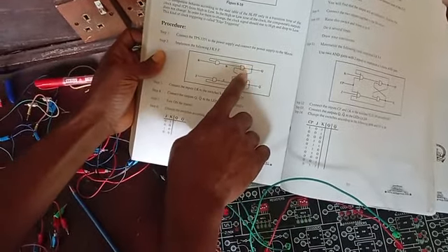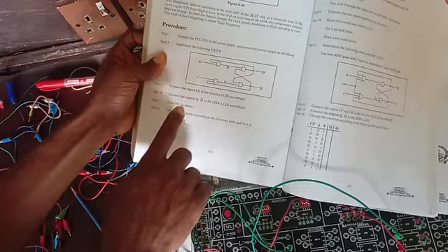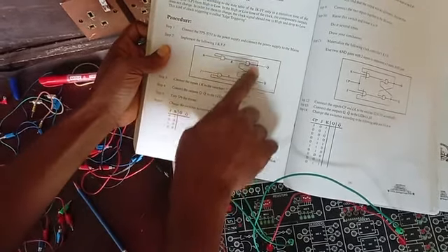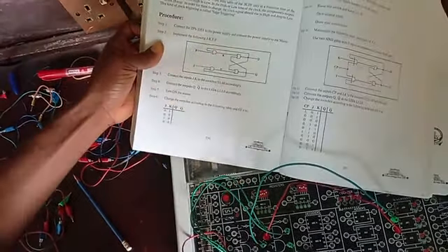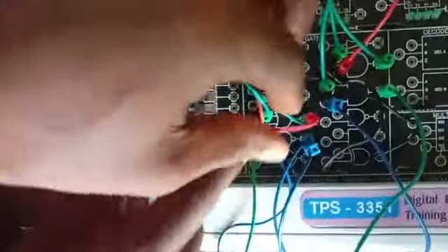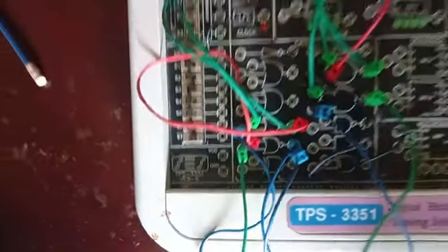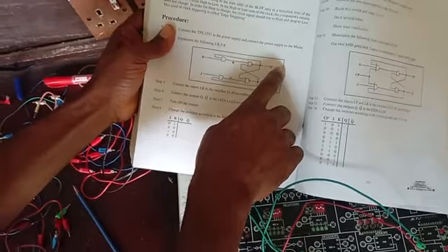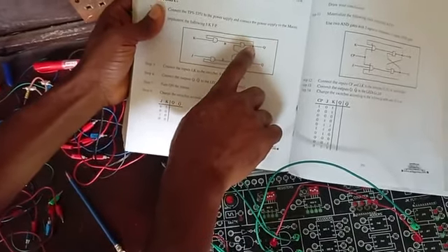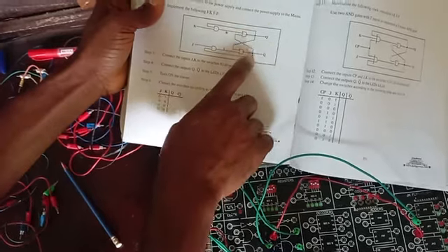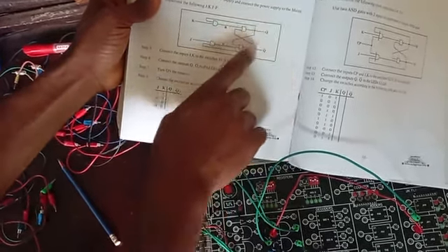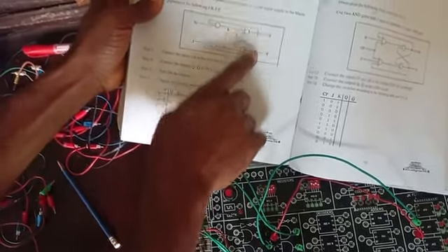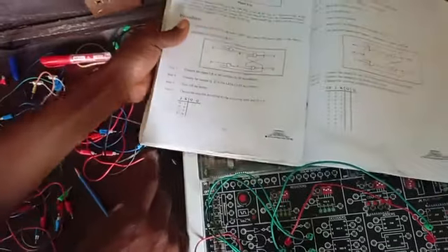So now we need. That means at the back of this NOR gate we have two wires now, 1, 2. So you can see at the back of it we have two connectors. It's done. So we need another connector, make it 3. That will be the back of that NOR gate, which will go to Q and Q bar from our logic gate. We are going to feed the back of the NOR gate with Q and Q complement.